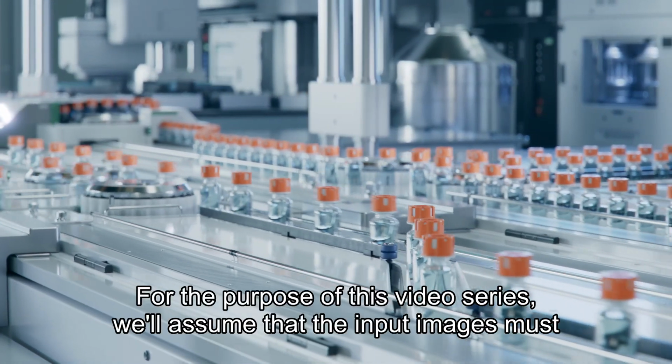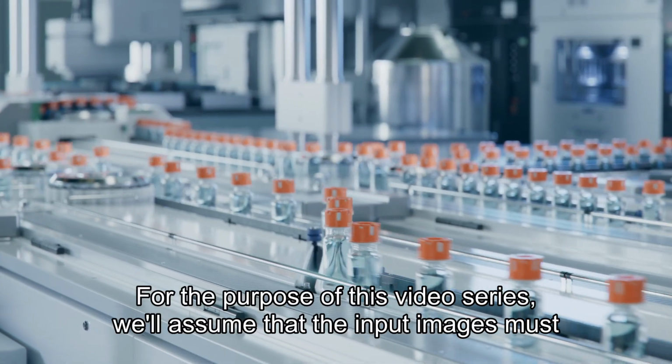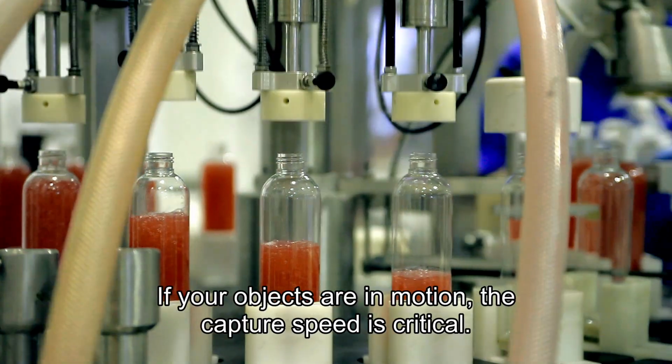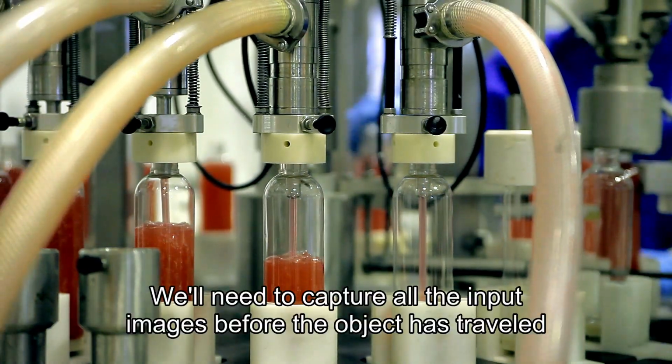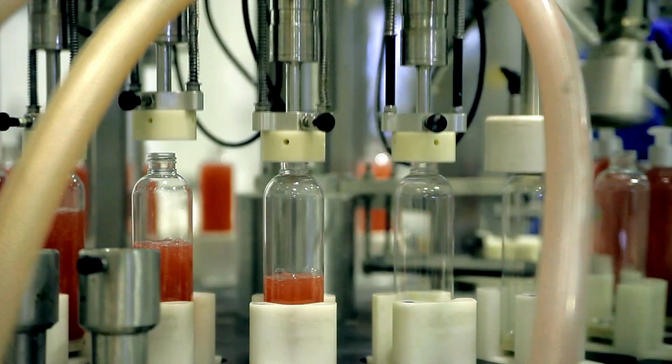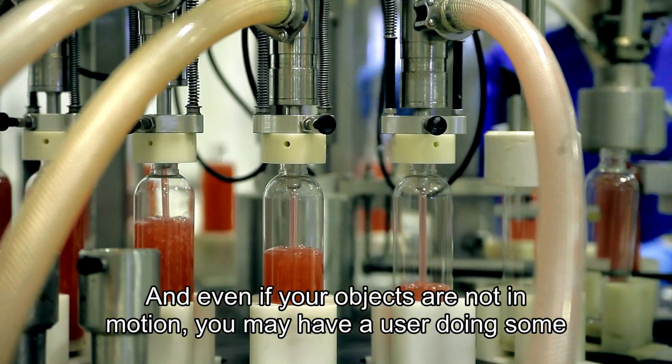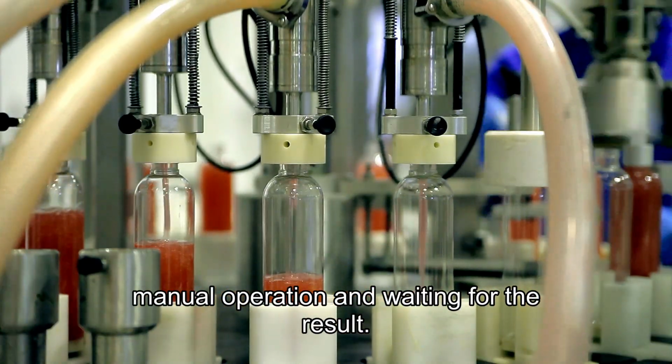For the purpose of this video series, we'll assume that the input images must be captured and processed quickly. If your objects are in motion, the capture speed is critical. We'll need to capture all the input images before the object has traveled outside our field of view. And even if your objects are not in motion, you may have a user doing some manual operation and waiting for the result.